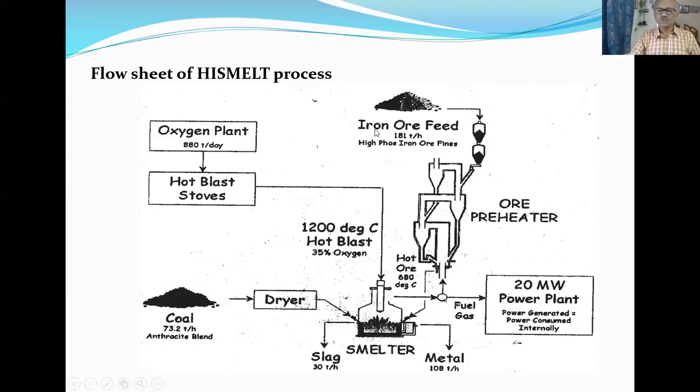And also another thing is that the iron ore fines are injected, okay, at a high speed into the liquid metal such that the capture capacity becomes high. Similarly, coal also in a fine state you can inject into the liquid steel. Otherwise, you cannot dump the fines over the liquid. It will never melt. It will just float over it. Okay, so you have to inject it at a very high speed, and in that case, your melting efficiency, capture efficiency of the liquid also becomes very fast. Very fast dissolution will take place.